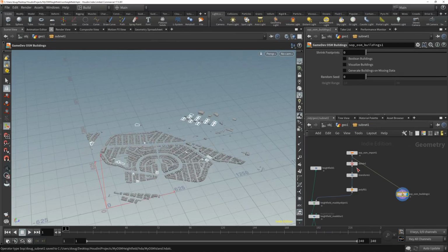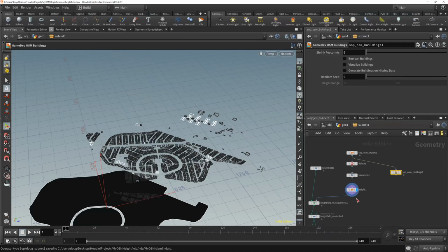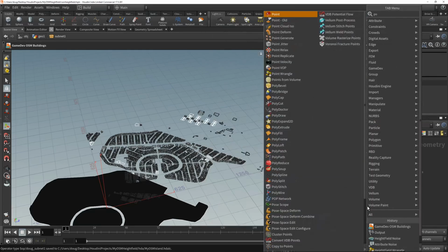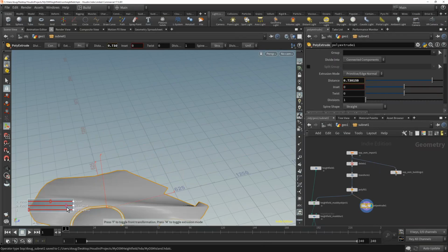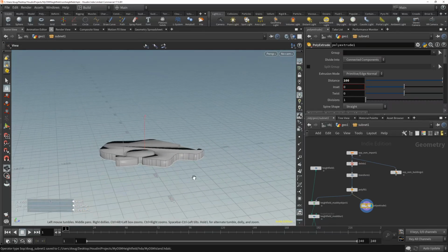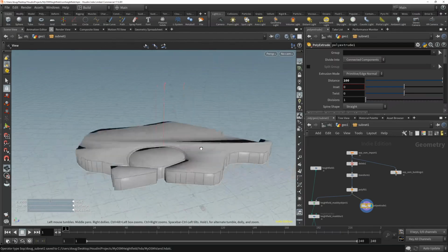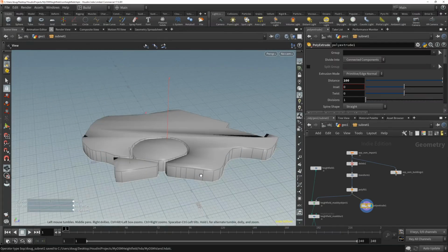And that's pretty much it. So to do that, I need like a bounding box of what's in and what's out. So I'm going to use this polygon that I had before, do a poly extrude. I'll just extrude it up, say 100, doesn't really matter. So here's my bounding box for buildings that I want in the level.